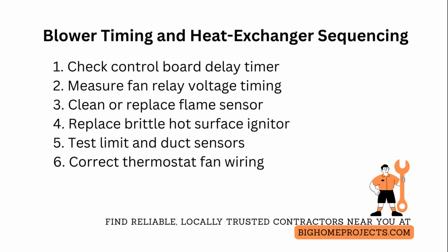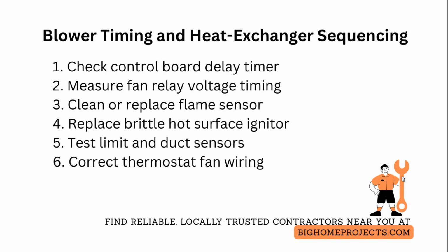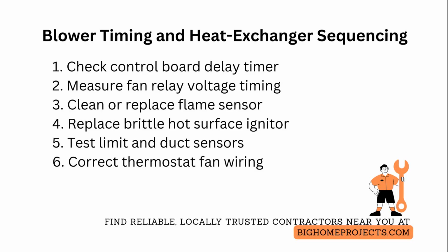Verify the limit switch and heat anticipator settings, or the high limit and duct sensors on newer units. An out-of-spec sensor can signal the control to start the fan too early. Test resistance and temperature response with a multimeter and replace if off by more than the manufacturer tolerance.